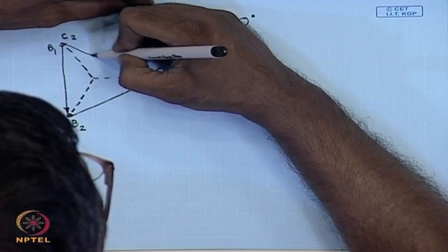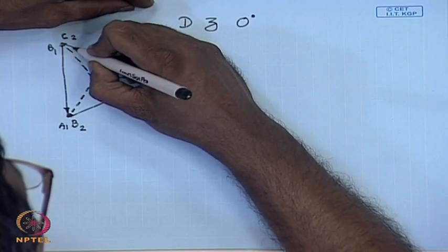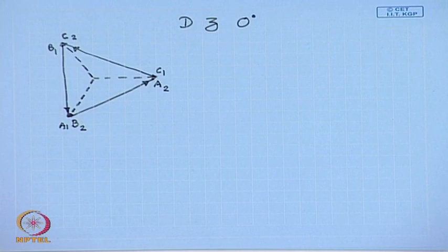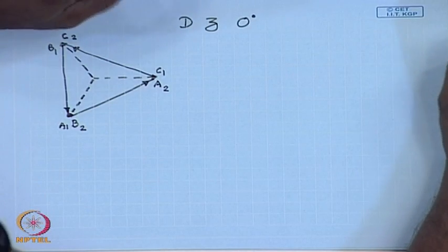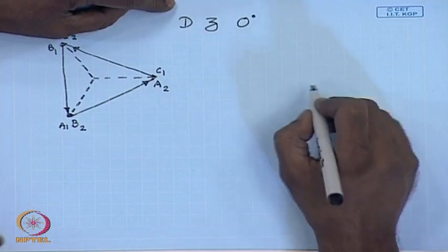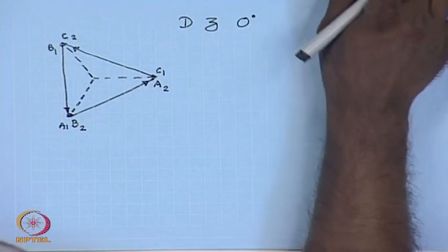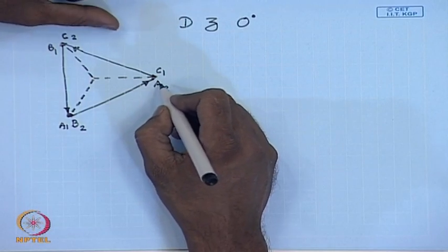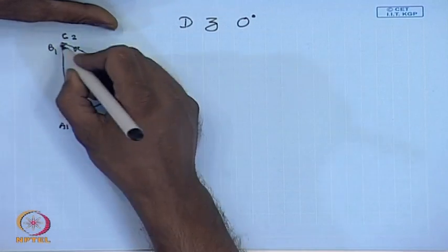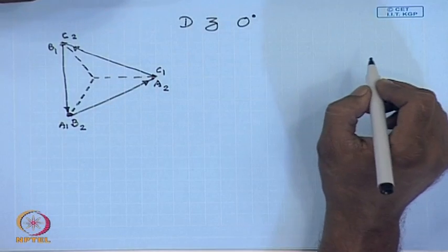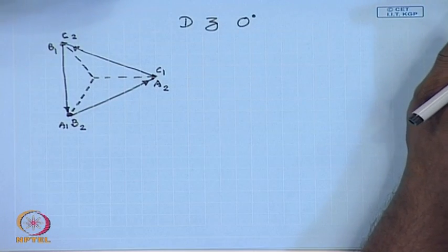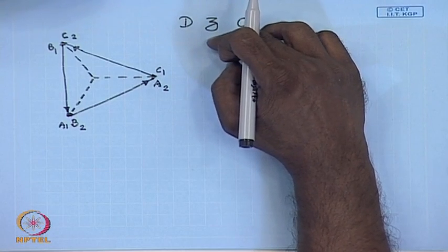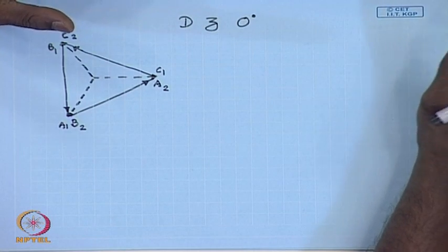These are the winding voltages. Now, this is the delta side connection A2 B2 C2. Now, it is to be understood that in a zigzag transformer each of the secondary windings has two parts.